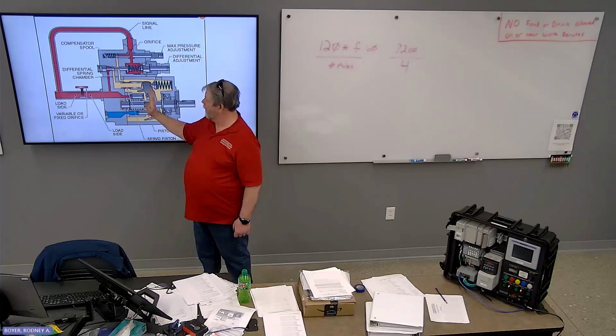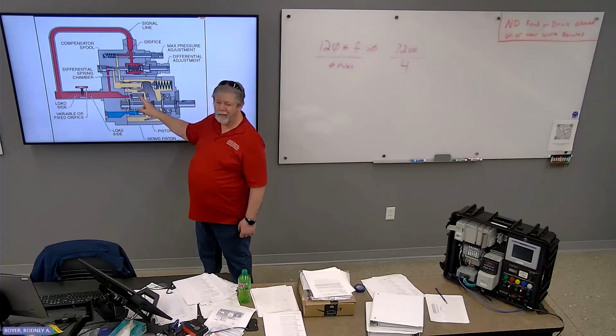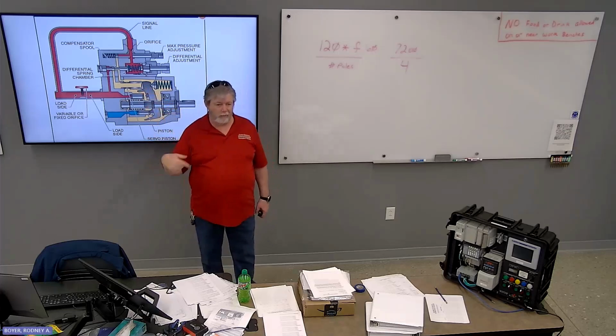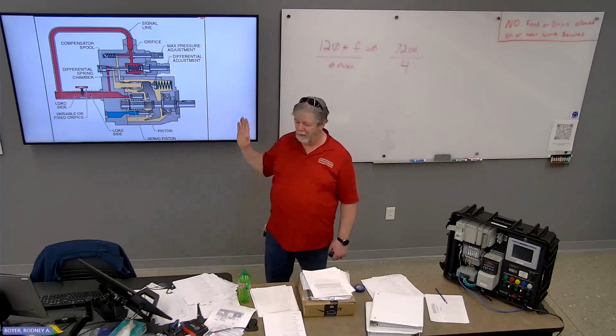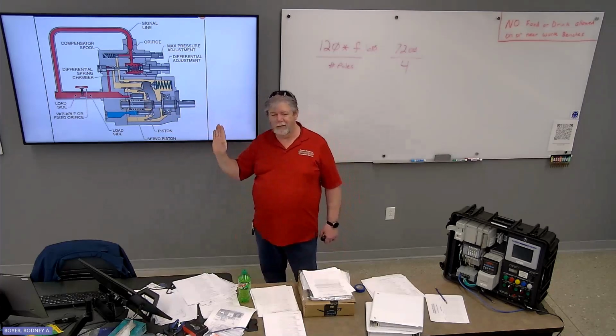The less angle it has, the less these pistons move. The more angle it has, the more they move. So they displace a lot more fluid when the plate is tilted than when it is straight up and down.